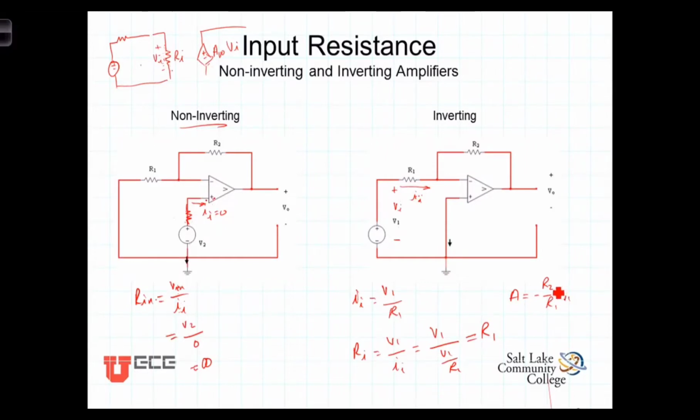First of all, it's tough to get highly precise, big resistances. But the other problem is that when we start having resistors on the order of megaohms, the current flowing through here is so small. After all, that's what we were trying to get it to be. We wanted that current to be small, so we made these resistances large. The problem is, as we have said before, the current going into the terminals of the op-amp is really small, but it's not 0. In fact, the currents coming into the op-amp might be on the order of a few tenths of a microamp.